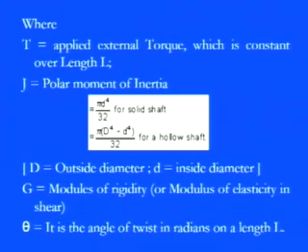And in that also we found that G was there, the modulus of rigidity, or the modulus of elasticity in shearing action. Since we are only assuming elastic deformation, this G is valid, in which the shear stress is proportional to shear strain, and it is also a property of the material. Which material are we using? Generally we use an elastic or ductile material, in which the percentage elongation measures the ductility property.